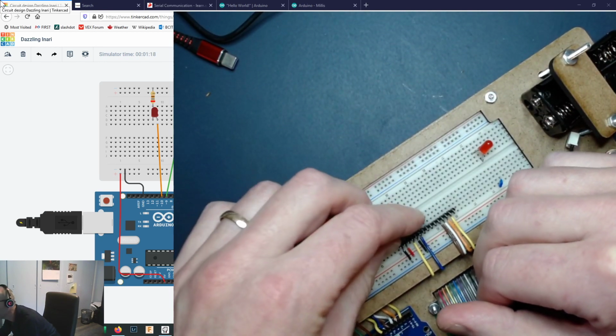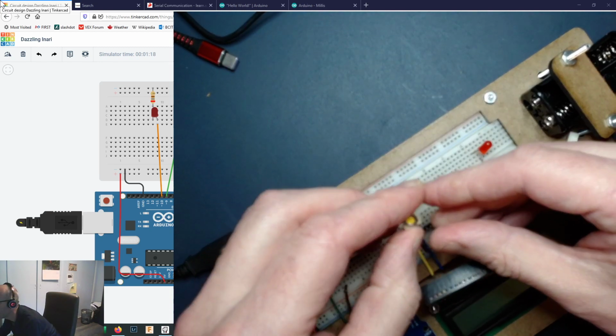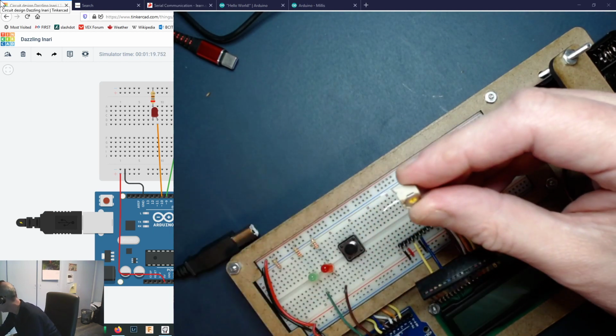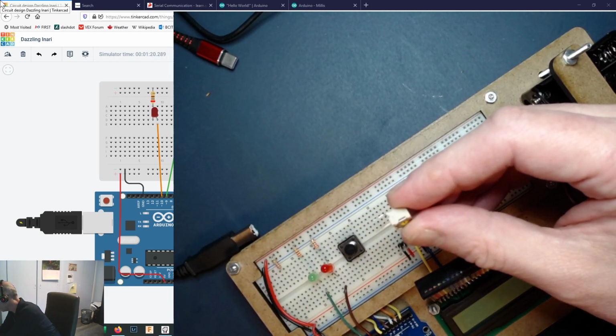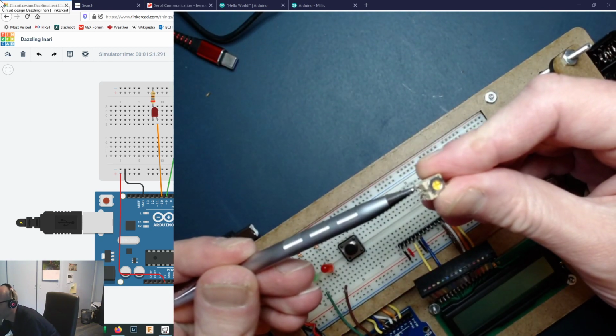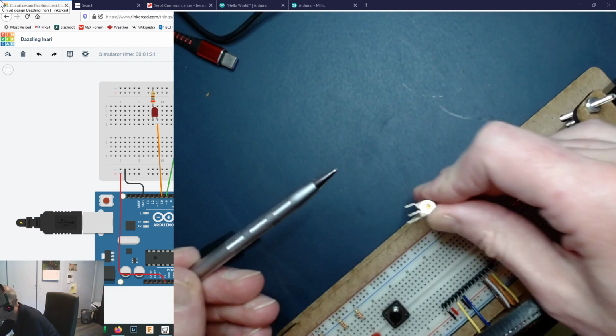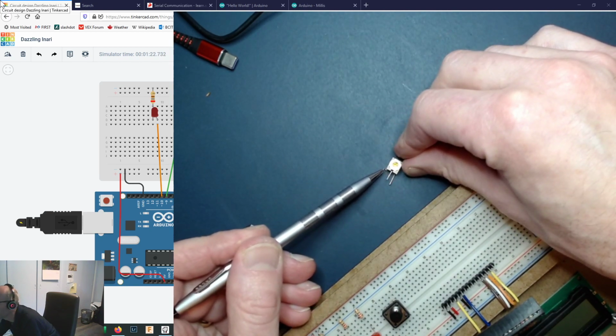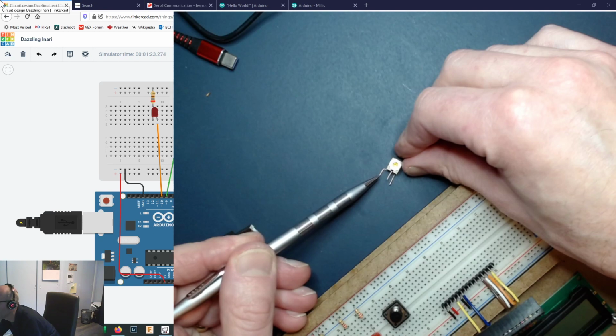Okay, now also in your kit is this little potentiometer right here. And I used a pair of needle nose pliers to take one leg, and doesn't matter so long as it's one of the two outside legs on here. Let me just set that down right there. And you can see that I put a slight bend and I move that over 2.54 millimeters.